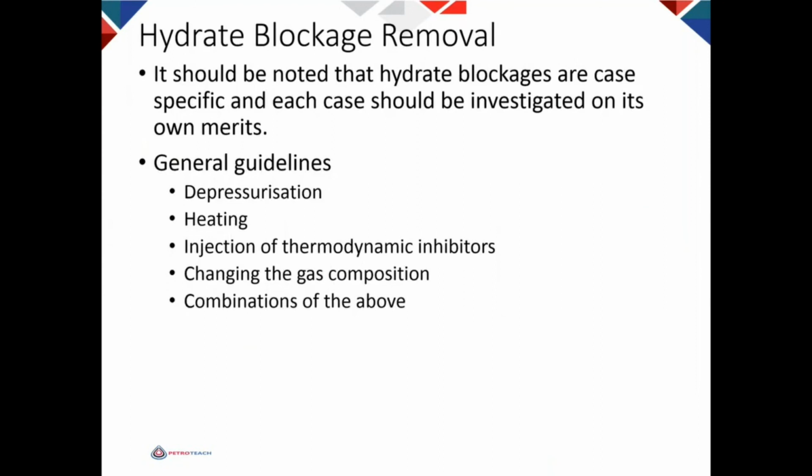The last slide: the different options for blockage. The popular one is depressurizing. Use heating, injection of thermodynamic inhibitor. We can change the composition of the gas, or a combination of the above.